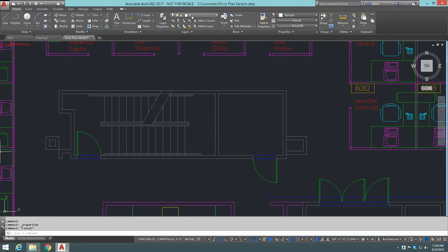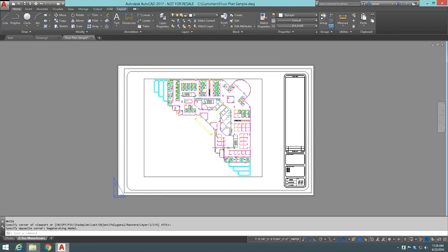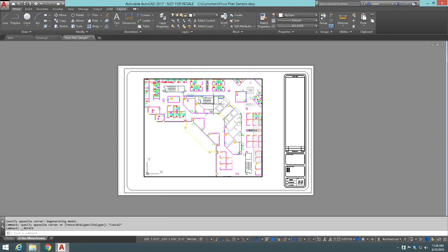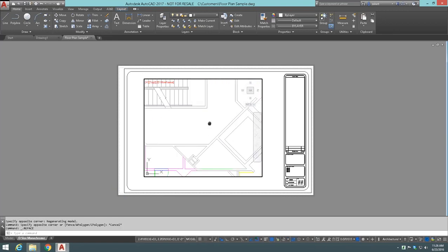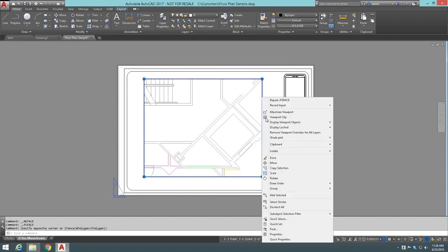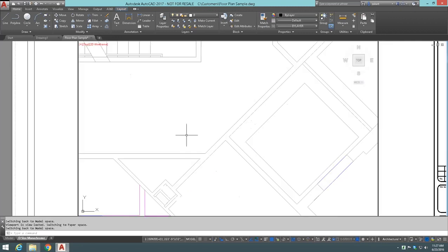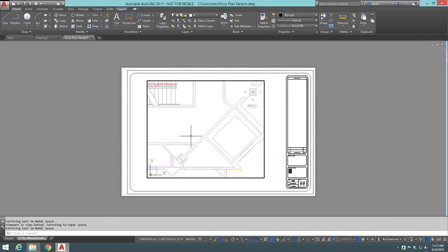There we go. Okay. So to expand upon what Mike was just talking about here, let's make a viewport. MV is a command you can use to quickly make a new viewport. Let's say you're inside a viewport and you've zoomed way in, and to preserve the scale, you have display locked the viewport so that you can't accidentally be in model space within the viewport